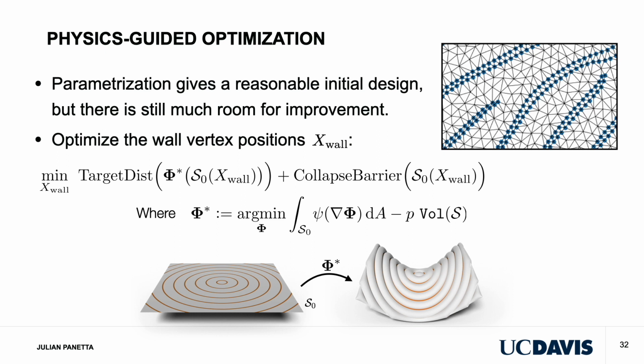The collapse barrier term here prevents triangles from degenerating during the optimization, and also prevents the fusing curves from shrinking below the laser spot diameter of the fabrication machine. An additional smoothing regularization term prevents the fusing curves from becoming significantly more jagged during the optimization, and promotes roughly uniform spacing of the fusing curve vertices.